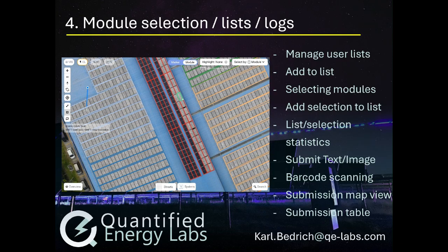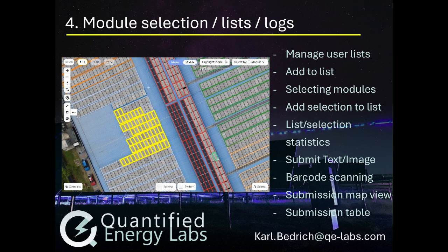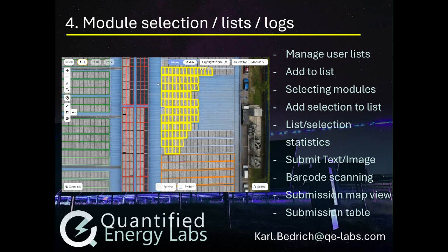For this, there's the selector tool that I just clicked. Here you add and create a polygon with simple mouse clicks, and a double mouse click will finish the polygon and add the result to a selection. You can also hold down Shift and drag the area that you want to select. That's of course much easier if you align the rotation first according to your modules.